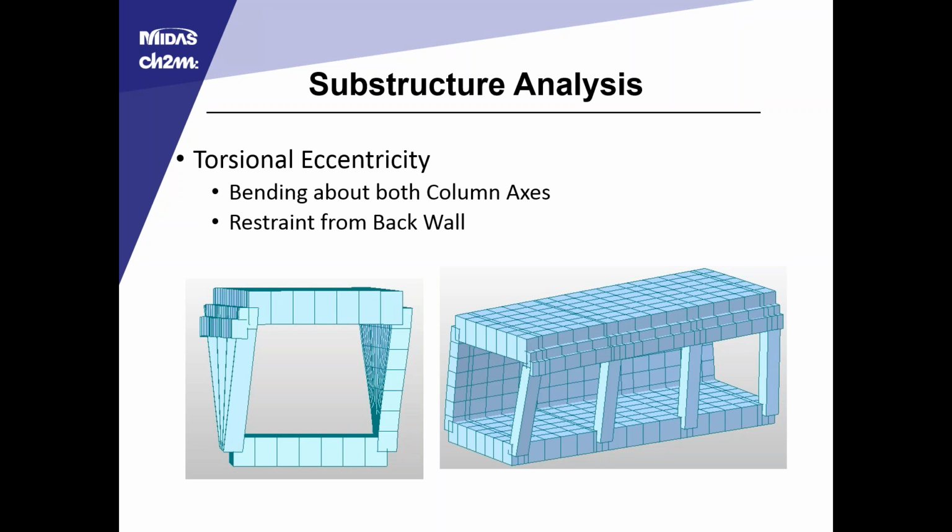So the question becomes, is the change in the interaction significant in that it allows the column to maintain more shear capacity, or does the back wall absorb the additional shear capacity because it is a rigid element? By inspection, because this element is so rigid, we can anticipate that having that back wall there will provide a better seismic response. But because the action on the column is different, it was something we needed to investigate.